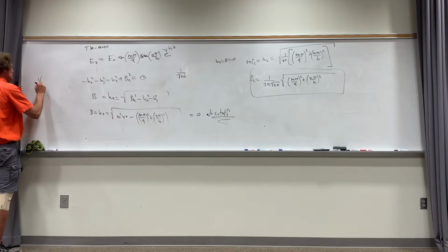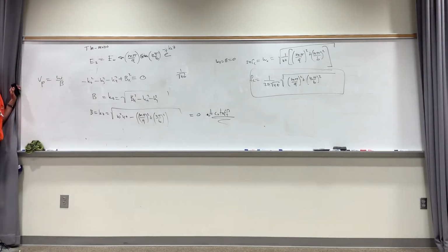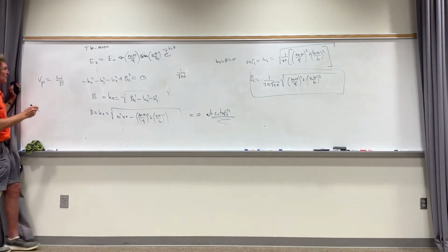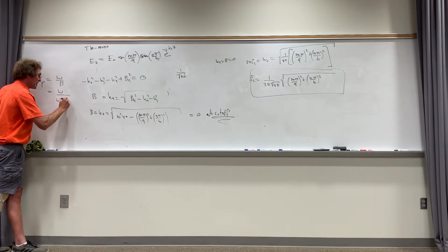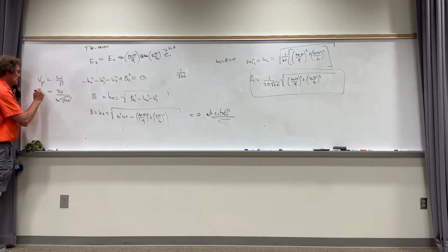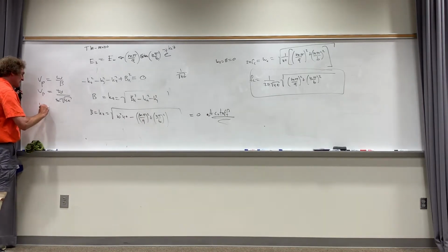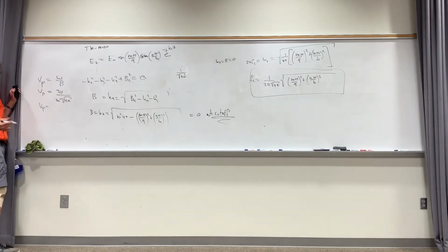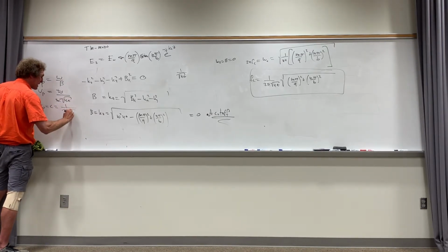Remember what phase velocity was? It was omega over beta, wasn't it? Well, in lossless media, it's omega over omega square root of mu epsilon, right? So y'all see the omegas cancel in that one. That's phase velocity. What if it's free space? What's the velocity of light in free space? c, or 3 times 10 to the 8. Well, that's 1 over the square root of mu naught epsilon naught.